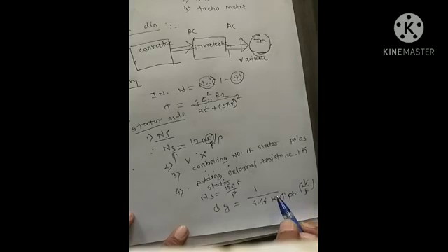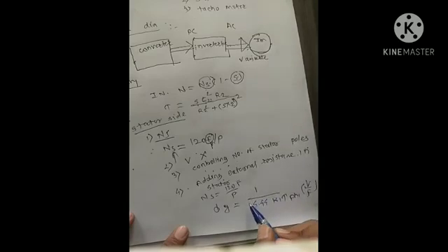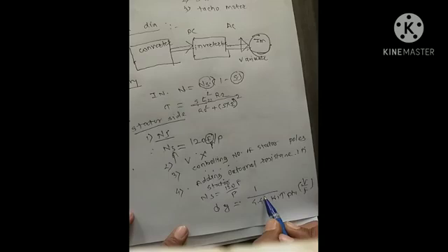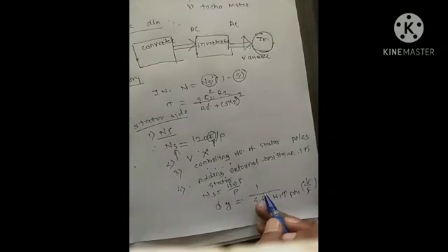If only the supply frequency is changed, the phi g value is affected. If phi g increases, saturation of stator and rotor core occurs. Due to this, the magnetizing current also increases, and the power factor of the motor is highly affected.